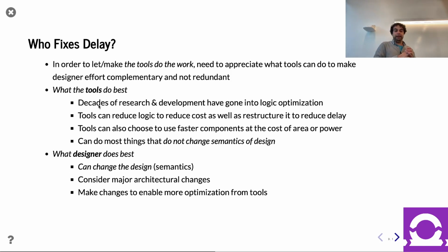Now, sometimes it's as simple as figuring out a way to insert a register along the critical path. But other times you have to do a much more major, much more fundamental architectural change. And once you make those changes, then you can let the tools run again. So you can see this process: run the tools, get results, understand the results, think about the design, change the design, let the tools run again. Hopefully the delays are reducing, right? You start to see where time goes, right? Cool. Questions?